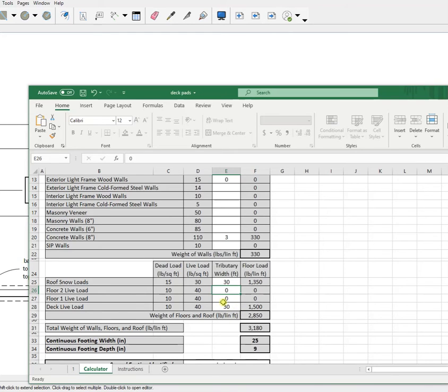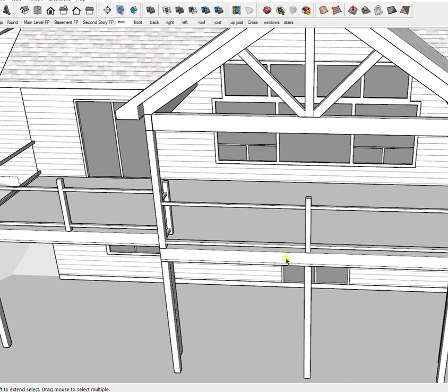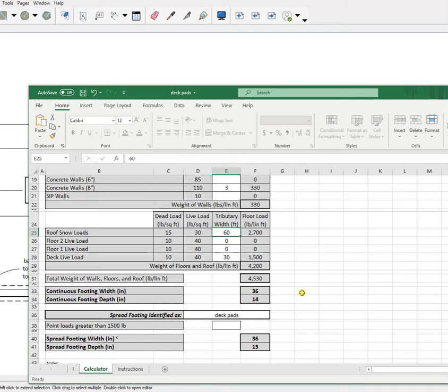It's a square footage thing. And then the same thing on that with, well no, the roof's a little different. See, the roof doesn't have a center bearing. That means it's half of the roof from here to here, and the other side is carrying the other one. So you would plug in the full 10 feet times the 6 this way. So they're coming up with a total weight of 4530.